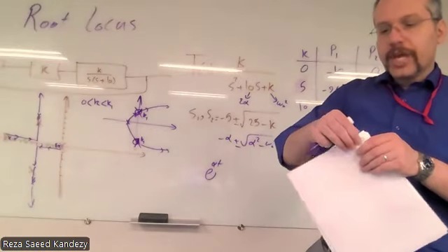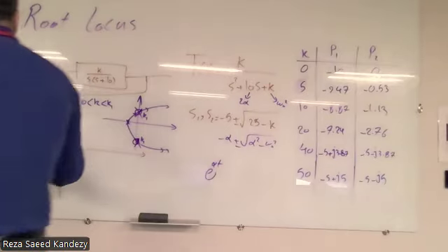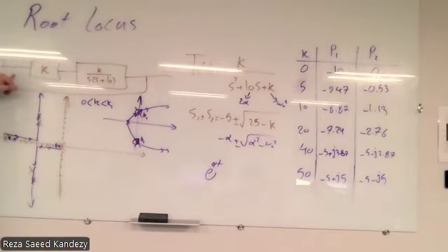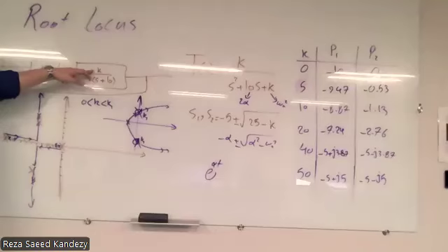So this is how we can use our plot diagram and the technique that we have for root locus. We said root locus is the closed loop feedback of our transfer function, and we want to analyze its stability when one or two parameters in our system are variable.